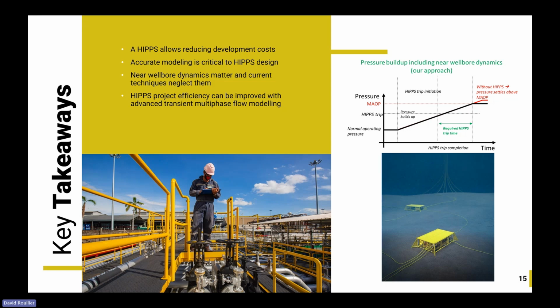I've seen certain operators assume a constant pressure boundary at the bottom hole. That's also extremely conservative, you assume constant reservoir pressure at the bottom hole. So depending on what your system is and the relative volumes of your pipeline and your wellbore and your reservoir, it may or may not make a difference.